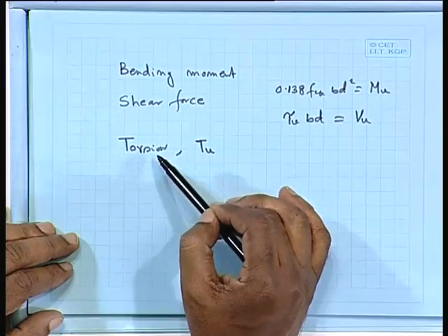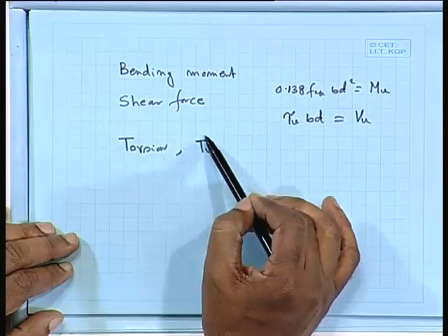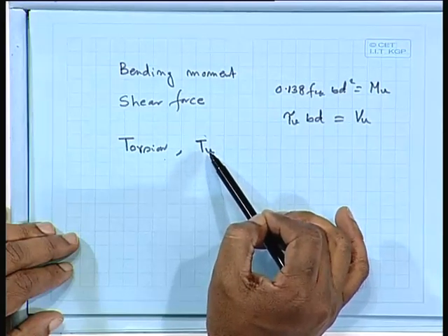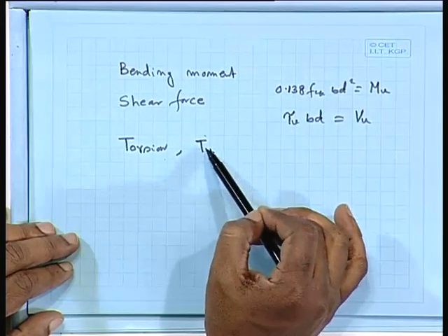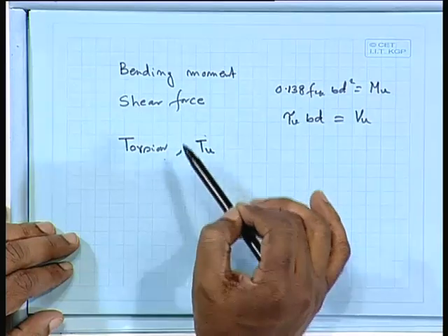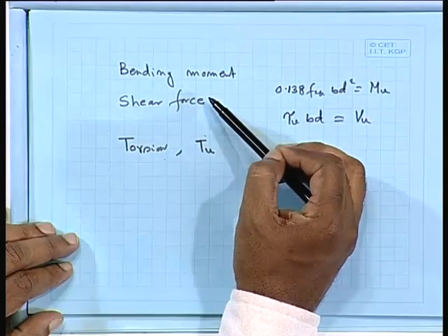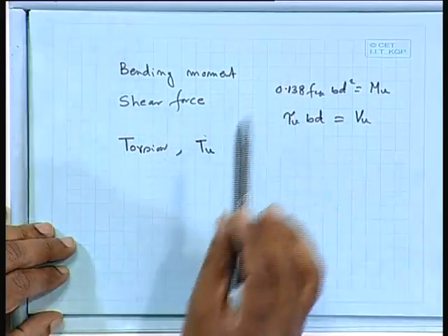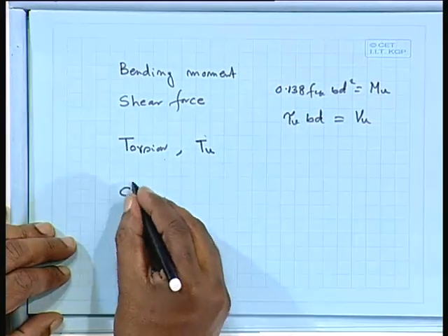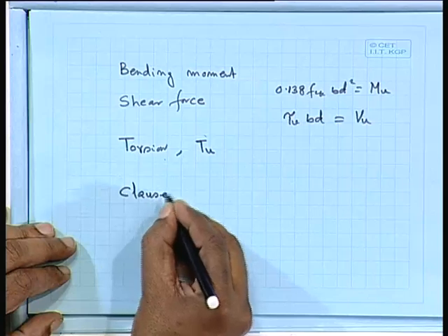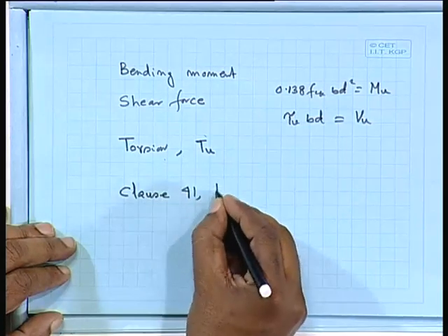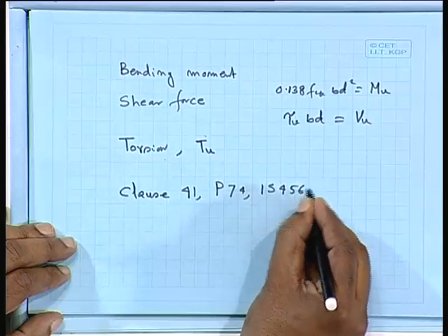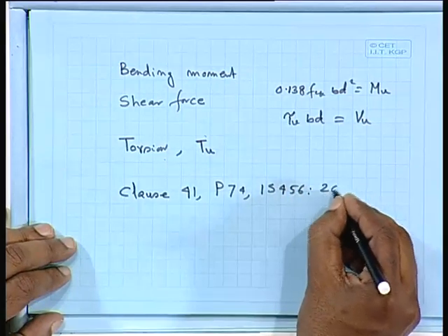So, what we shall do here, we shall find out how Tu is actually applicable, what is the equivalent for bending moment as well as for shear force. And this one we shall find in clause 41, page 74, IS 456 2000.